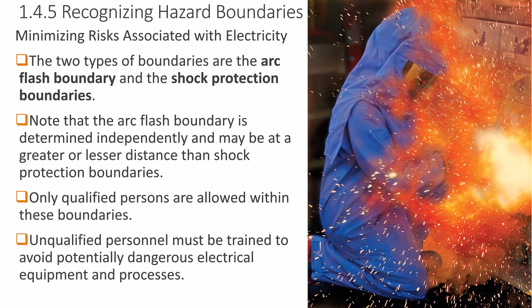So this person you see in this picture is in a special electrically safe suit. This is not a hazmat suit. This is an electrically isolating suit that can take the arc blast and some of the shrapnel that can fly against them, plus it's electrically insulating. And so when they don't know what the voltage is, or if they're not sure if the equipment is on and they have to go and check that out, they can wear the suit until they're sure that the electricity is actually shut off. And then they can take the suit off, just like the rest of the people who are going to work on the equipment.